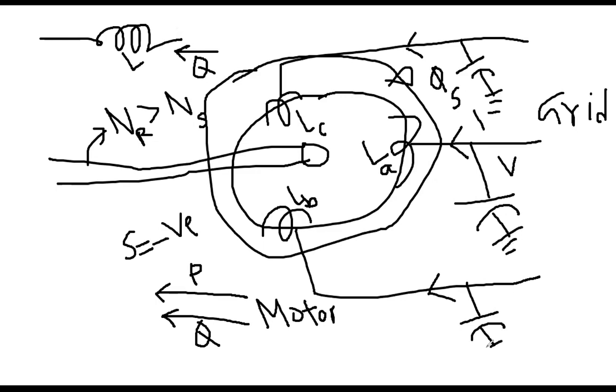grounded. So what is the benefit of putting a capacitor here? It will improve the power factor, as we learned in the three-phase circuit chapter. So we can put the capacitor to improve the power factor and to improve the voltage. It will support the voltage. It will not allow the voltage to go down, so you can prevent voltage drop. That's why, in the case of an induction generator, there is always a capacitor connected at the terminal. Everybody, could you follow me?